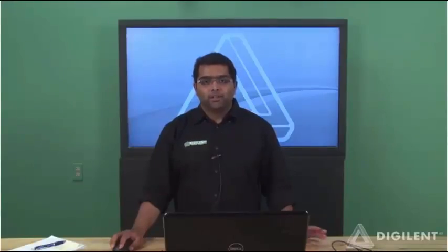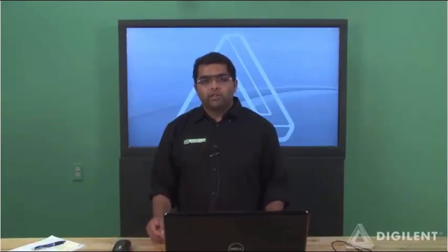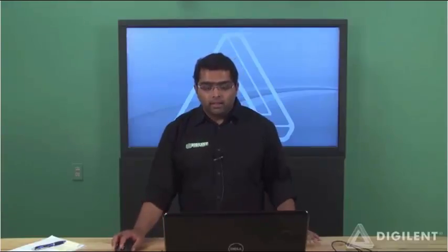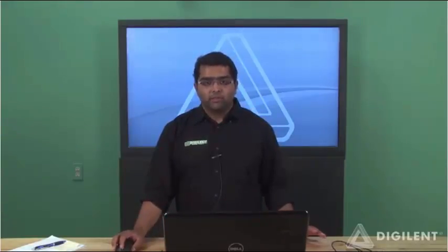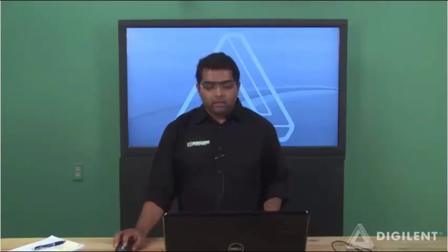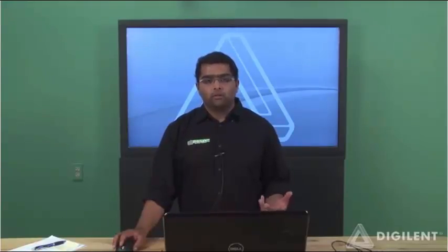Hello, my name is Varun and I'm here to introduce the new entry-level student FPGA board from Digilent, the Basys3. The Basys3 has the Xilinx 7 series FPGA, the Artix-7, designed specifically to work with the Vivado Design Suite. The Artix-7 FPGA is optimized for low cost, low power, and small form factor.